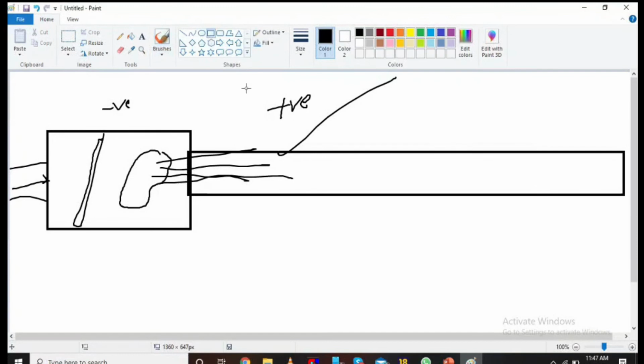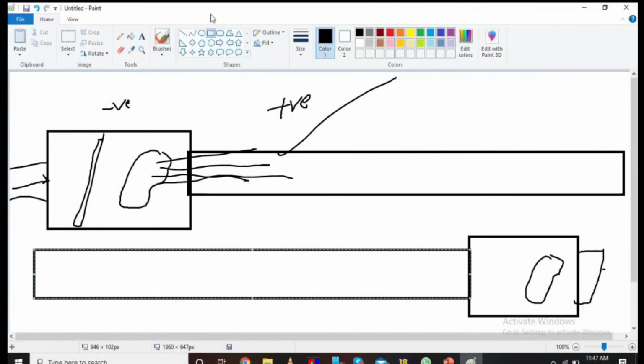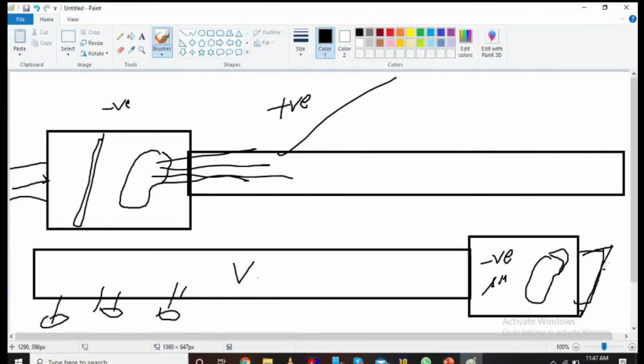Now I will tell you one more scenario. You have a machine here, so you have a fan here, and this is your outlet. This is your ventilation scenario, exhaust, kitchen exhaust or toilet exhaust. You'll be having so many exhaust diffusers, all connected to the exhaust duct. So during this time the negative static of the fan should be more. Once it reaches the fan, it is not going to push anywhere, it just needs to push outside to the atmosphere through the outlet.